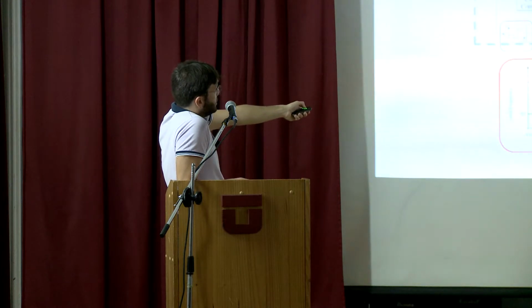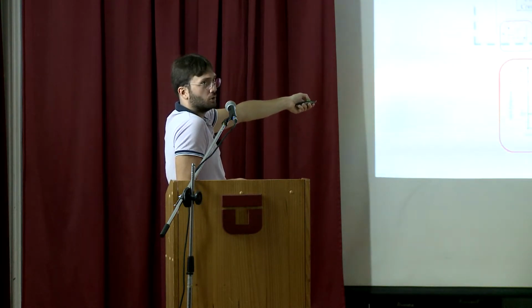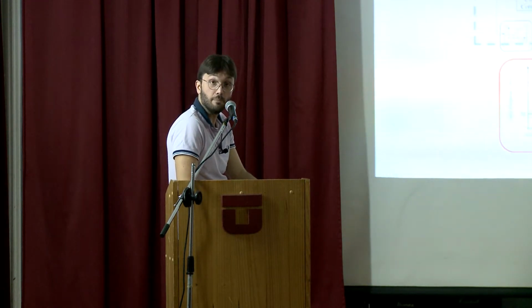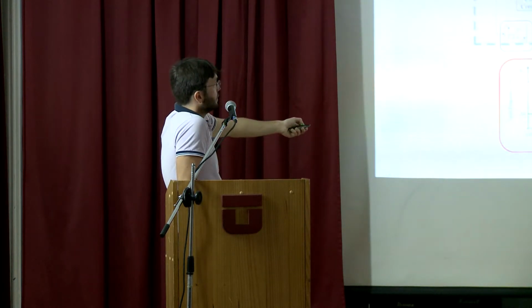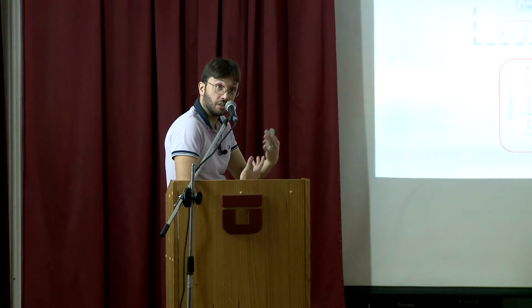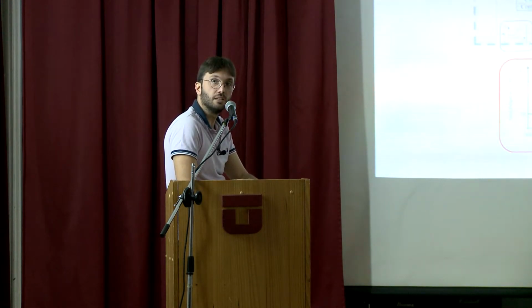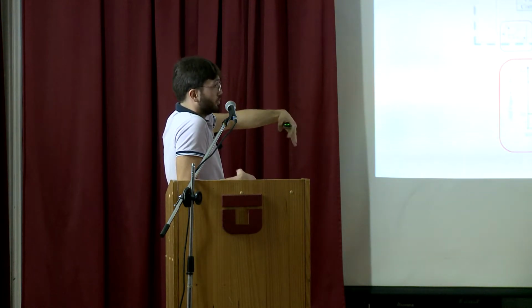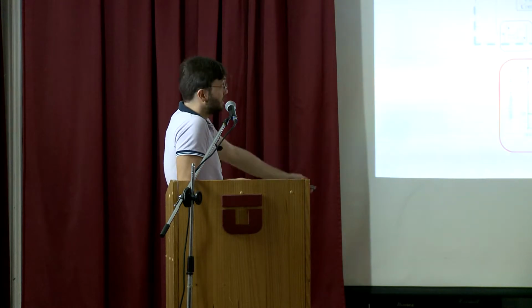So in the distributed generation case, what do I have? I have some current controller, and then I have some voltage controller for the DC-link. So basically what we saw in the demonstration down in the lab, that there was the converter implementing some MPPT, and then, okay, there was the predictive control. This is a general scheme. It can be predictive, it can be anything, but this is the usual way that distributed generation is realized. Phase locked loop, so everything that a grid-connected converter needs.